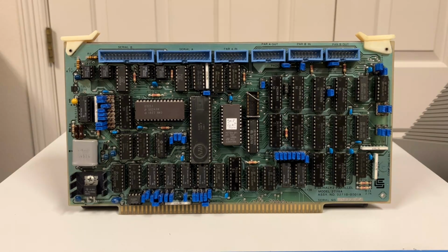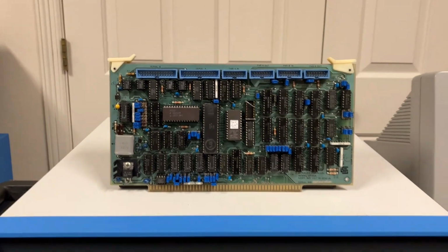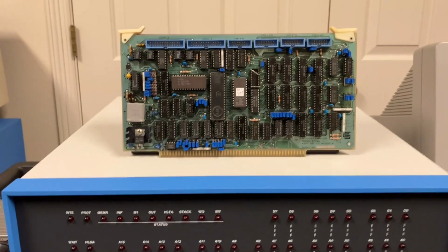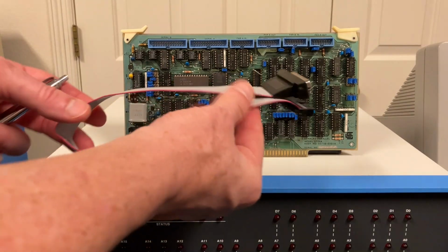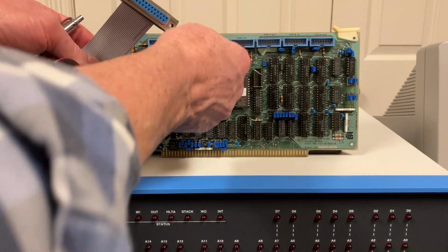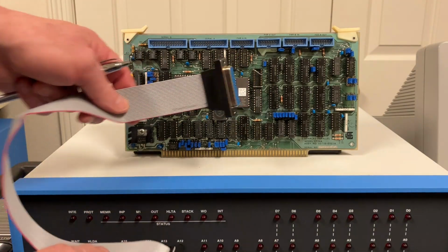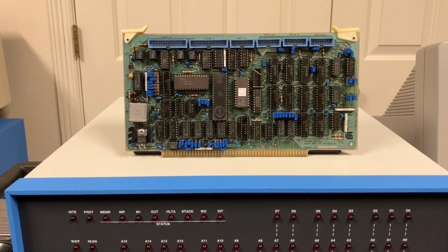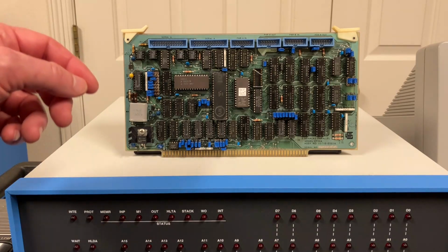Now, the serial data comes through these 2 ports up here. This second port is the one that's used for the cassette interface UART that we'll be using. That's a 26-pin standard IDC header, and that allows us to use just a simple ribbon cable like this to go to a DB25. Our socket plugs in there, and this goes back to the rear panel. The way this is wired, that straight through ribbon cable comes out as DCE, which again, that's what we need. That's how we expect our serial ports to be wired in the back. So that works out well.